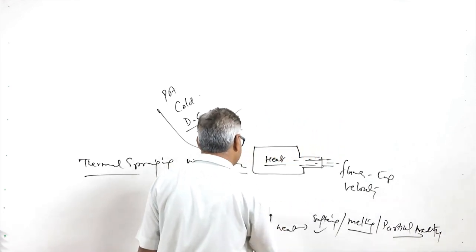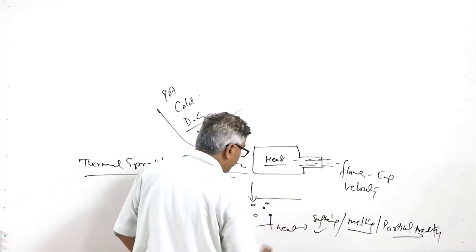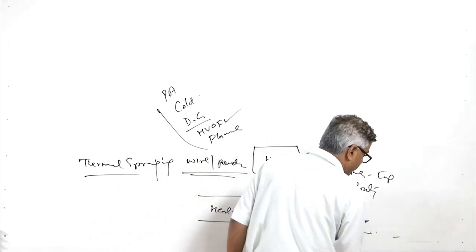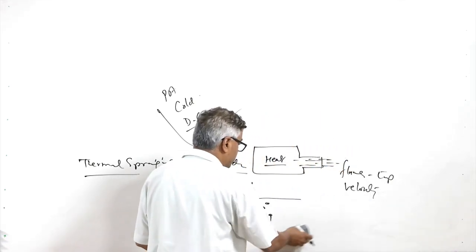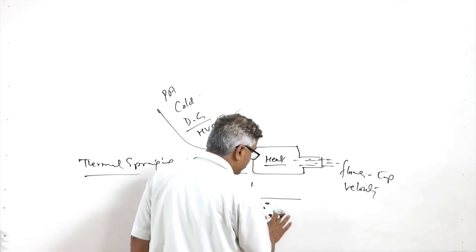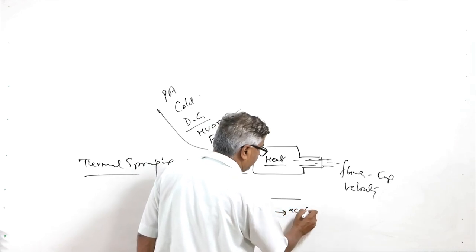So these particles, when they are added into the heat source, will be moving with the heat source. Depending upon the kind of heat source or suitable process being used, these particles will be heated, melted or partially melted, and then they will be accelerated.